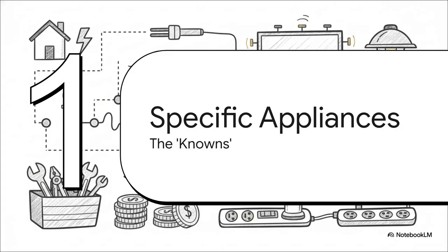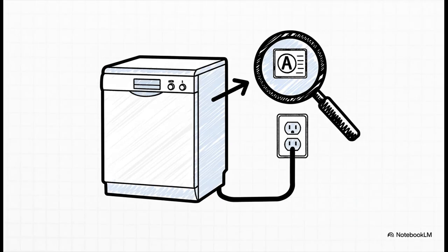All right, let's pop open that toolbox and grab the easiest tools first. We're talking about calculating loads for specific known appliances. See, when you know exactly what's going to be plugged into an outlet, the code gives us a super simple, direct path. And the rule here from 220.14(A) is just beautifully simple. If you have an outlet that's dedicated to one specific appliance, you just calculate its load based on the amperage rating of that exact appliance. It's right there on the nameplate, no guessing required. The load is what the machine says it is.